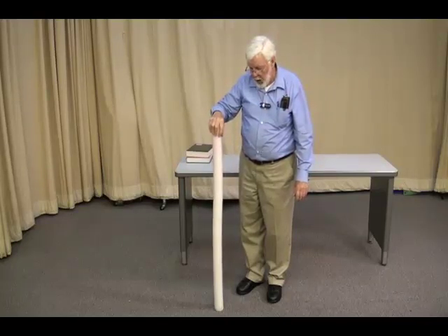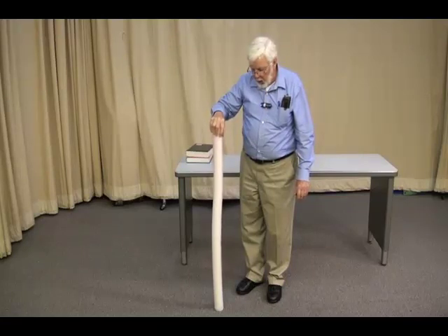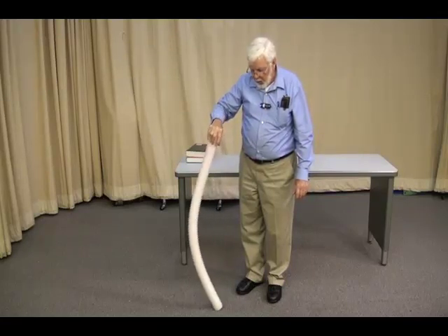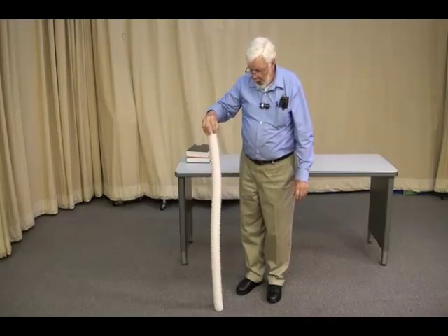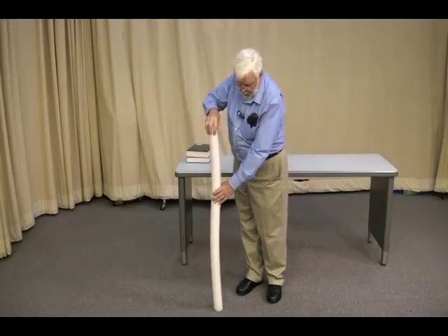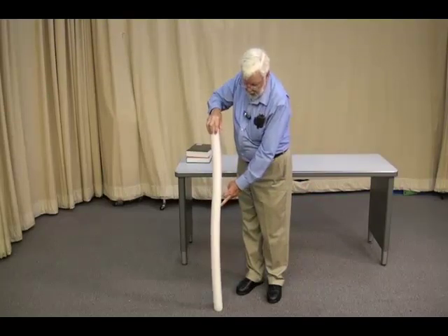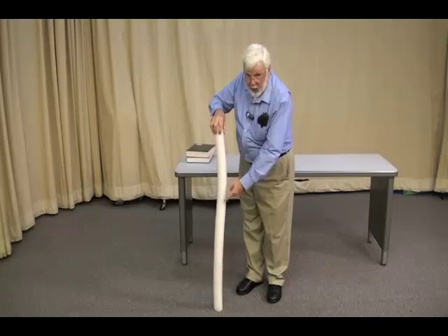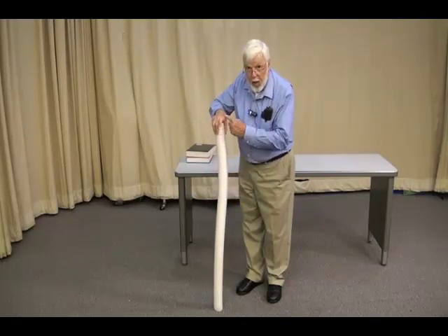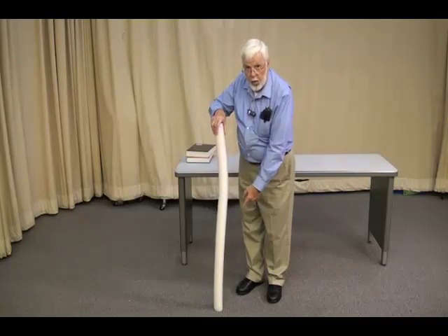Now I'm going to start putting a load with my hand on the top of this column. You can see it shaking slightly. And when that load exceeds a certain value, it suddenly bends and gives. What's happening is, as I push down on it, it's deflecting slightly. And as it deflects, the load which is passing through the center line of the column is now offset from the line from my hand to the floor.